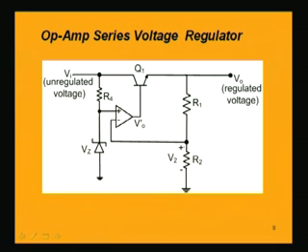The other point, which is connected across R2, will be dependent upon the output voltage, because what is V2? If we look into the voltage across this R2, this is V0 into, again voltage division like the earlier case, the voltage division is happening, V0 into R2 by R1 plus R2, this is the voltage V2.